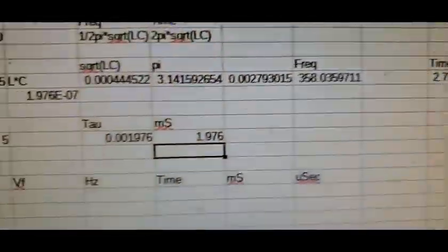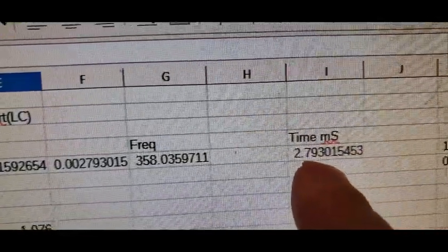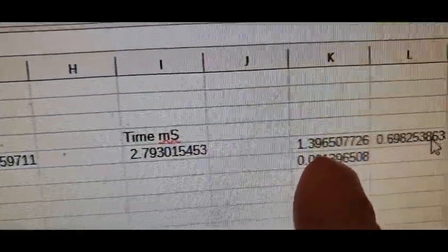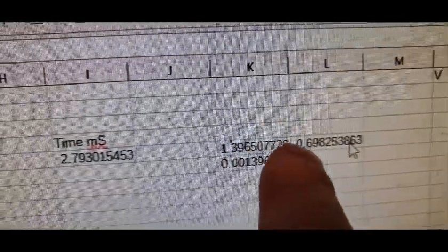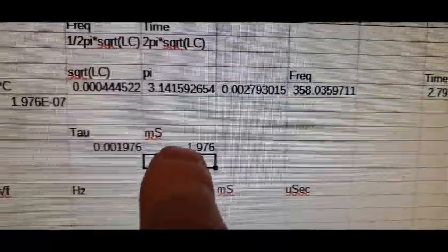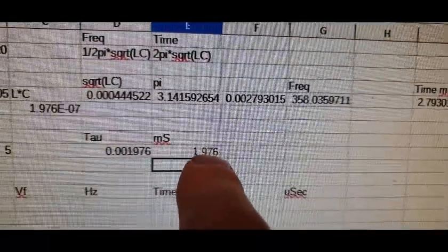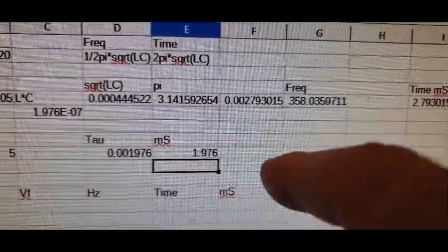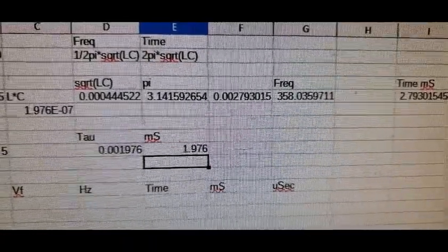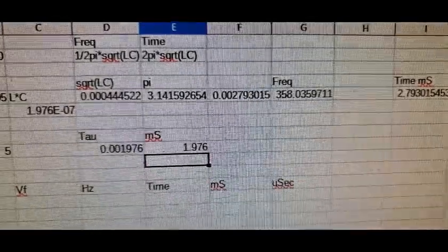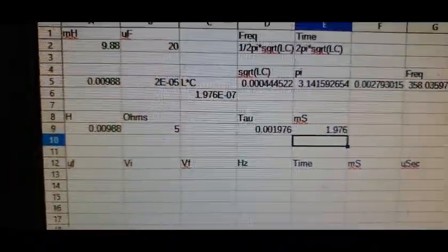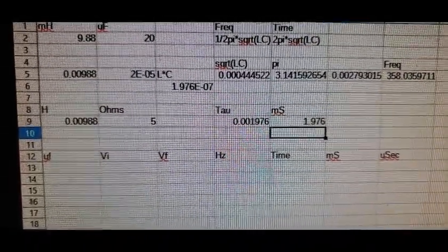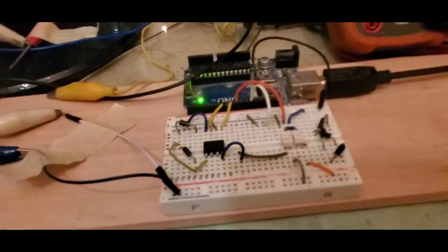Now we can already see that's wave crest to wave crest, but it takes that long for the cap to discharge. Or no, half of that time. So we're less than 1 tau time, and we're not really very far down along that curve where it starts to even improve more. So it probably won't be very good, but let's see what it does.